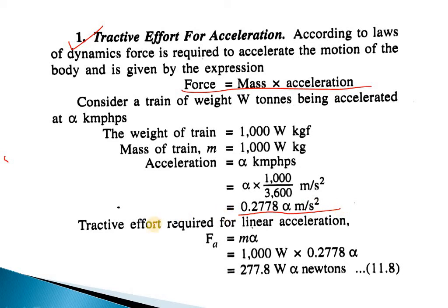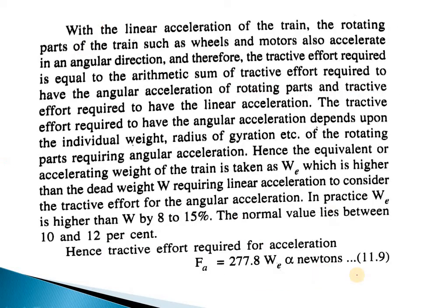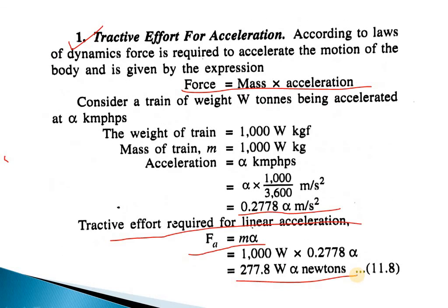And the tractive effort required for linear acceleration, that is Fa equals m into alpha, equals 1000 W into 0.2778 alpha. So ultimately it will be 277.8 W alpha newtons. So this is the force for linear acceleration.